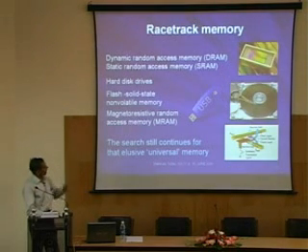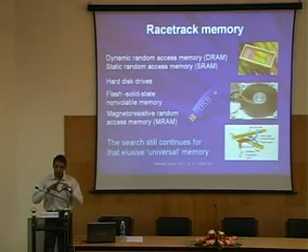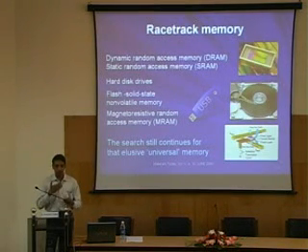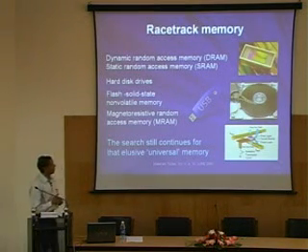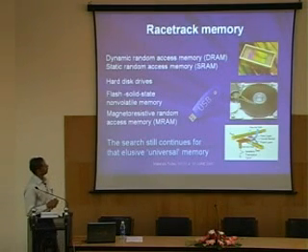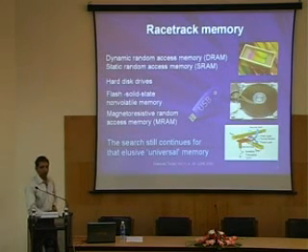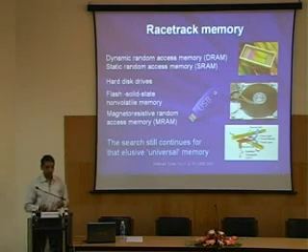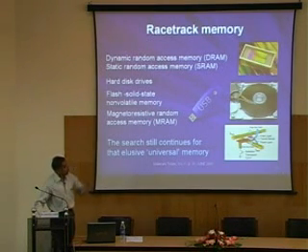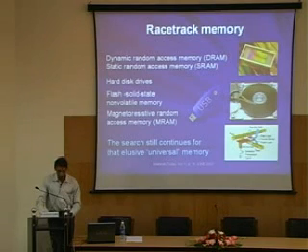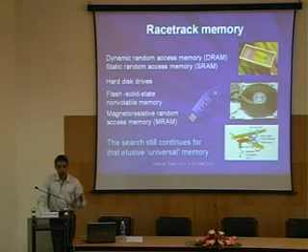One of the recent applications of the nanowires is not only to build electronic devices, field effect transistors or diodes. Recently IBM has come up with a new memory technology known as the racetrack memory using nanowires. The conventional memory, semiconductor memories or magnetic memories, they have their own limitations. For example, if I am using these random access memory, SRAM or DRAM, these memories have to be refreshed about 1,000 times every second. That means you are consuming power in order to refresh these memories.